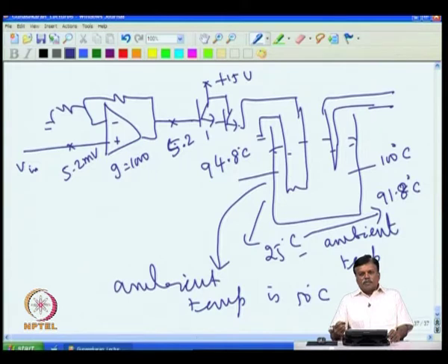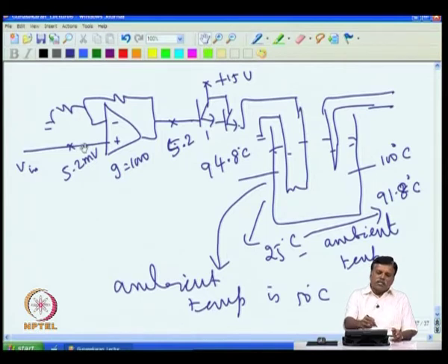This is happening because the heat coming in has to equal the heat going out, only at that point it stabilizes. Since the heat going out is changing, correspondingly the amount of voltage required is also changing, the amount of voltage generated by the error voltage, so the error voltage is also changing. So this is one of the drawbacks of the proportional controller.